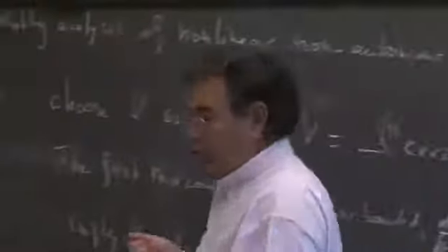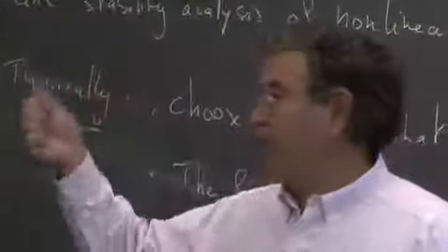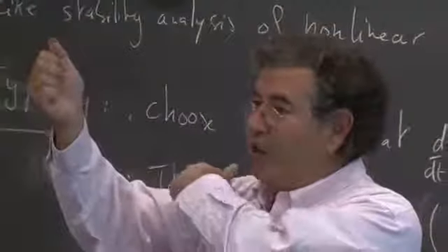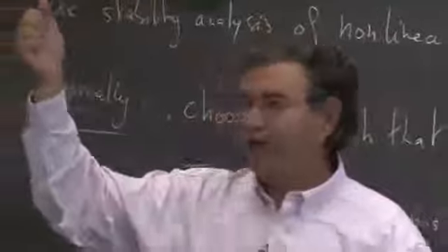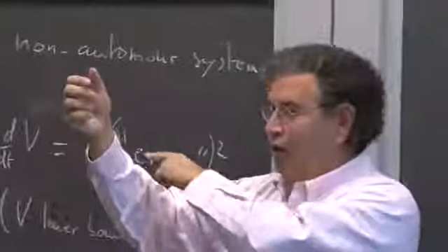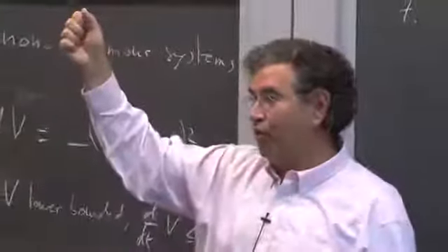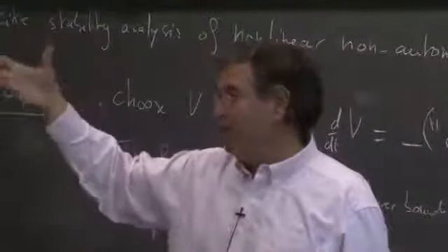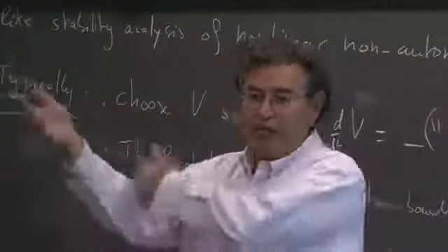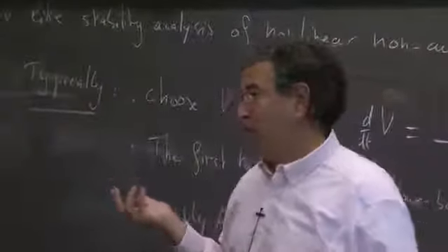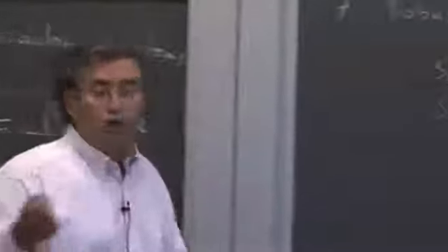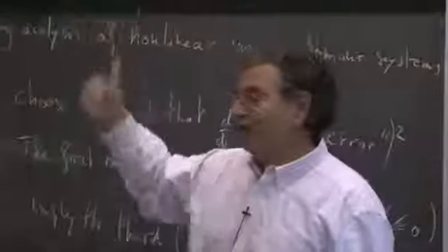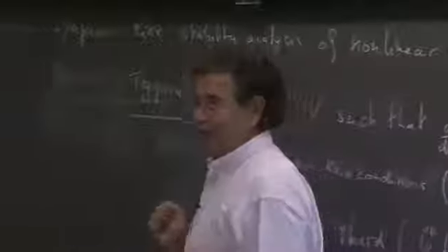For instance, if a robot picks up a baseball bat, the dynamics of the arm with the baseball bat is very different in terms of its parameters than without it, because the bat is of weight and size similar to those of the arm itself. So it won't be at all the case that you know the dynamics whether you have a baseball bat or not. You need to know much more about the bat.